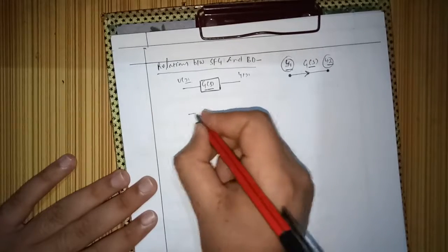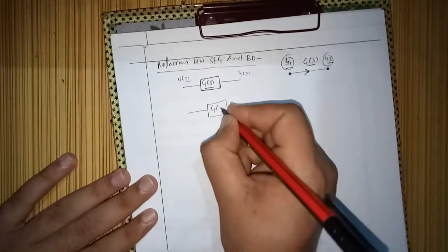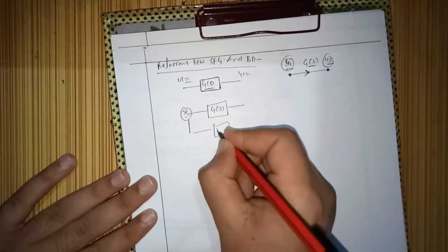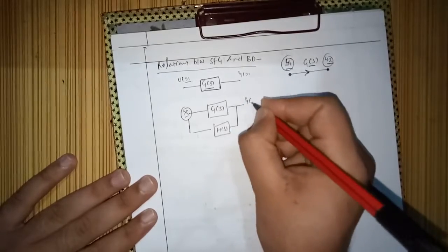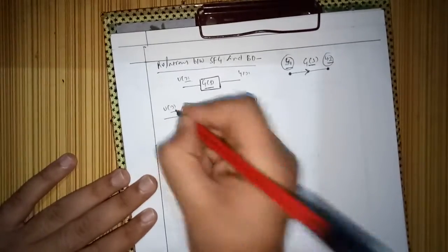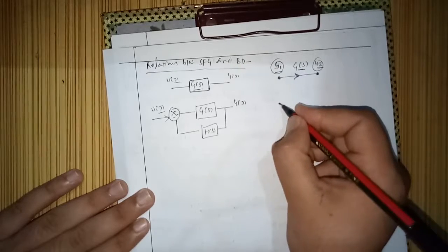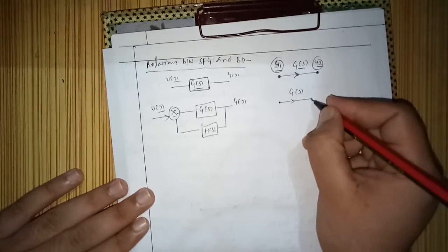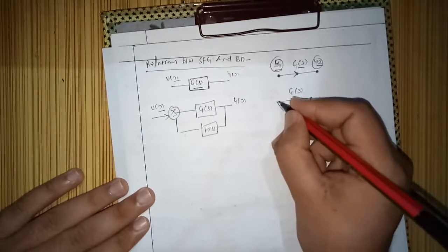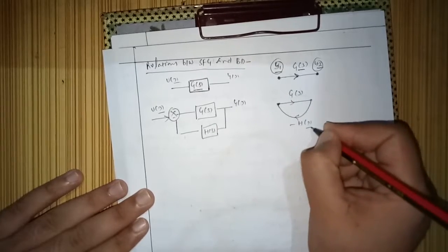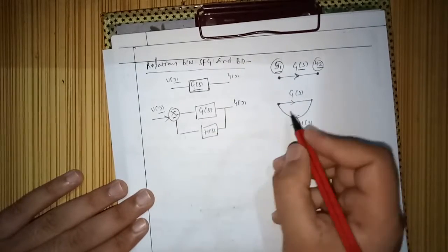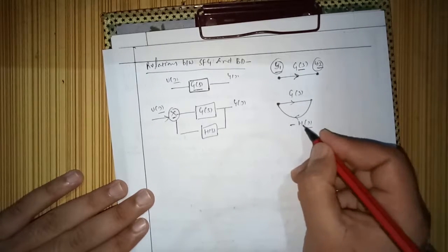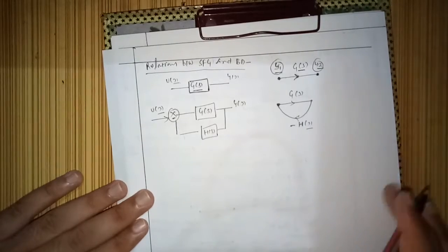Right? Now see, we have this G(s) and a negative feedback H(s), and I have Y(s), here I have U(s), right? So how do we represent this block as G(s), right? And this as minus H(s). Minus H(s) is because of this negative feedback. We don't have any mechanism to represent negative here, so I will represent minus with H(s), right?